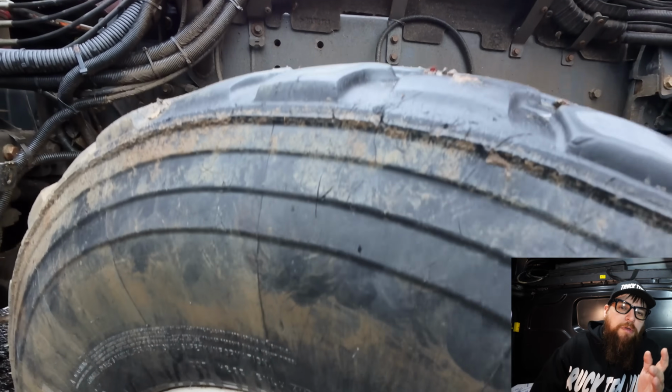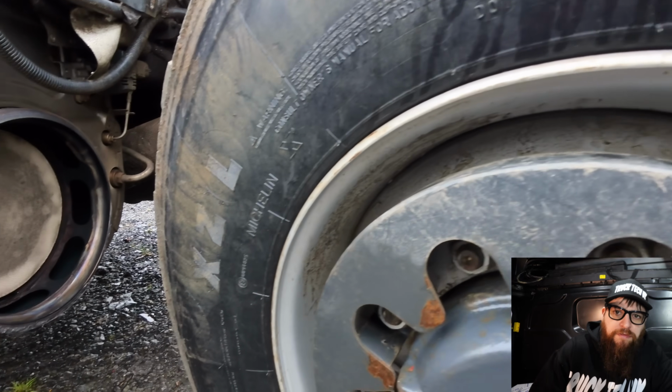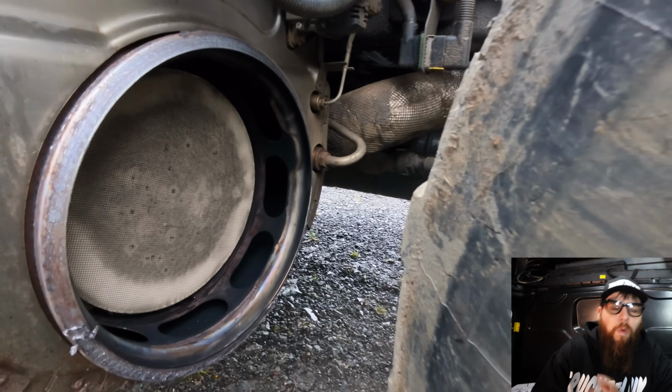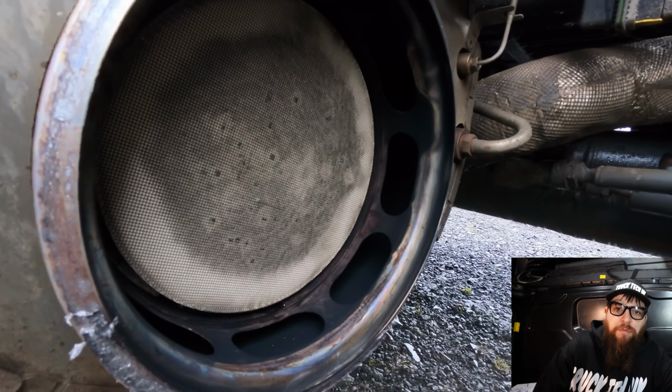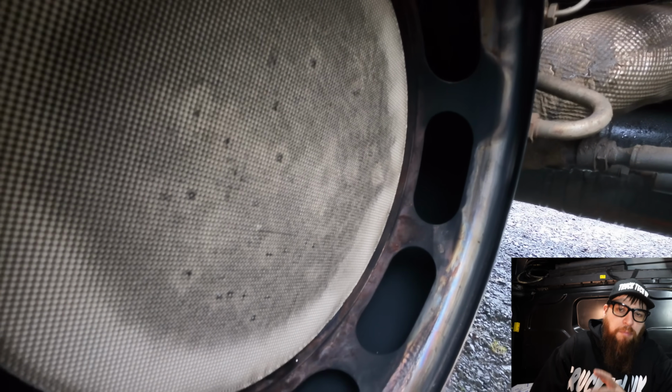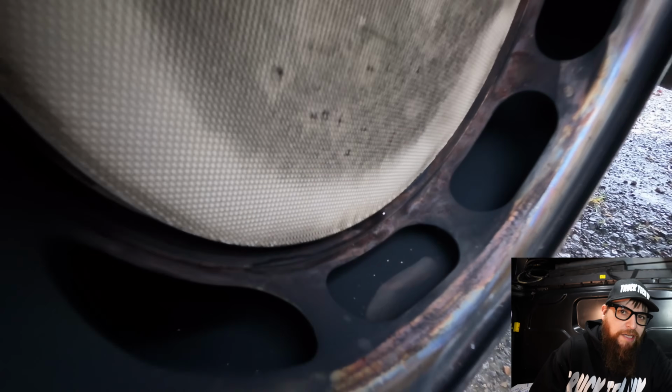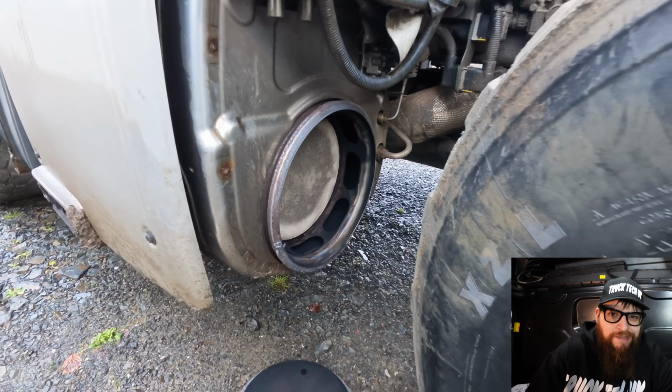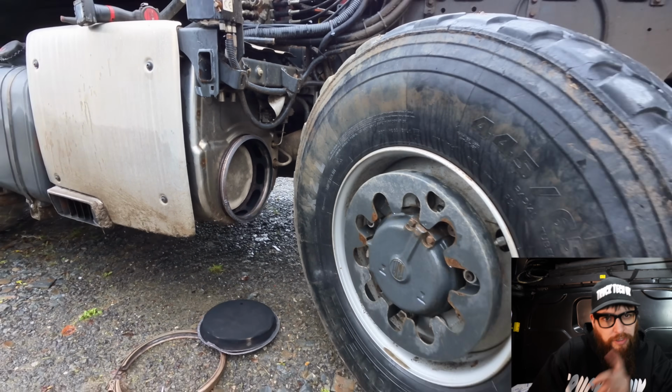I've saved you the pain of watching me strip off the cover from the DPF today, but we can see from the video why we're getting too much soot detected from the PM sensor before that gave up the ghost. I think this might need more than DPF seals. Luckily it hasn't moved, but from these pictures it certainly looks like it's got a bit more going on internally.